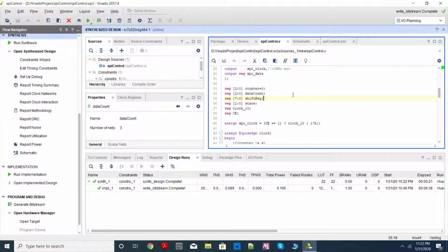That is very helpful in debugging, but once you find the problem, you should let Vivado do whatever it wants to do. Otherwise, that may affect the performance of your circuit. You are putting a constraint so it cannot completely optimize your circuit.